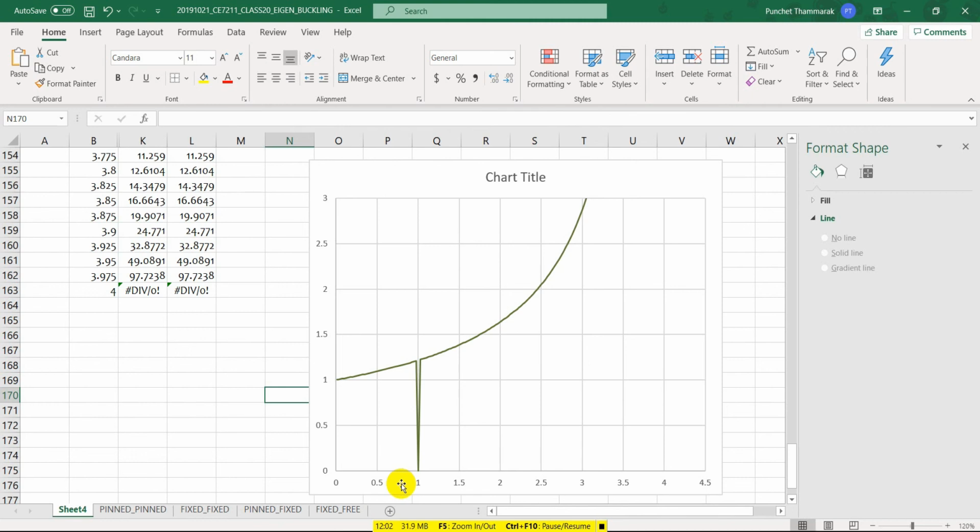For the y-axis, that will represent your deformed shape, but you shouldn't go with just y, because you're going to get the factor like the W and etc. Basically, you can determine the maximum deflection at the midspan of this fixed support beam under the uniform load without the axial force.